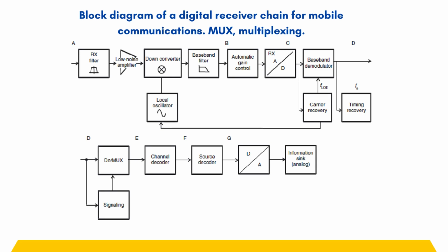the receiver local oscillator. The baseband demodulator in the receiver stage obtains the soft decision data from the digitized baseband data and hands them over to the decoder. The baseband demodulator can be an optimum coherent demodulator or a simpler differential or incoherent demodulator. If there are multiple antennas, then the receiver either selects the signal from one of them for further processing or the signals from all of the antennas have to be processed.